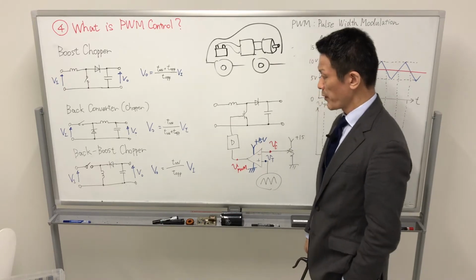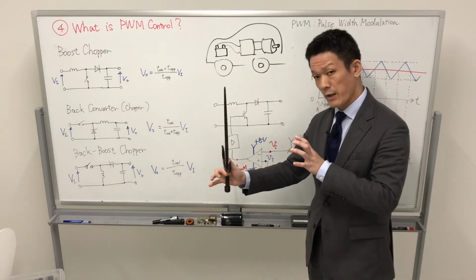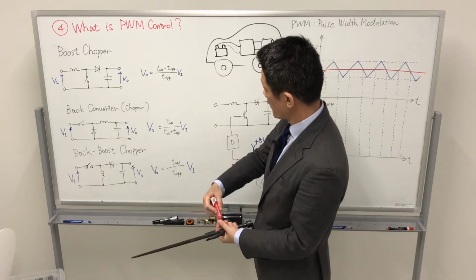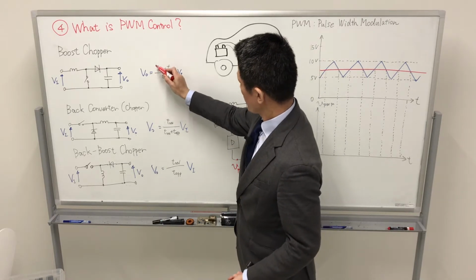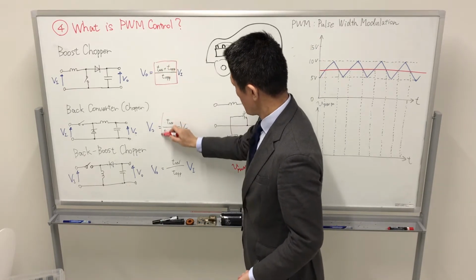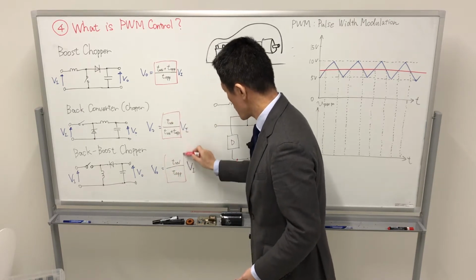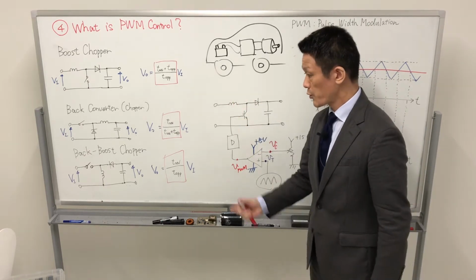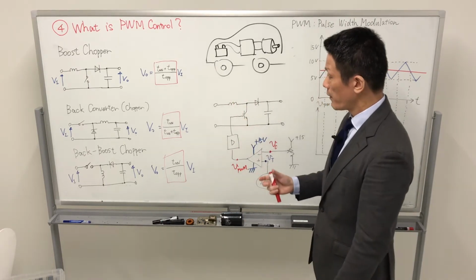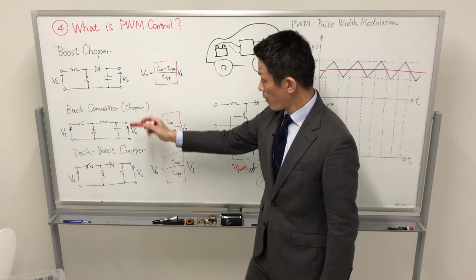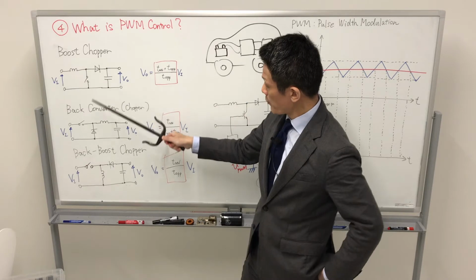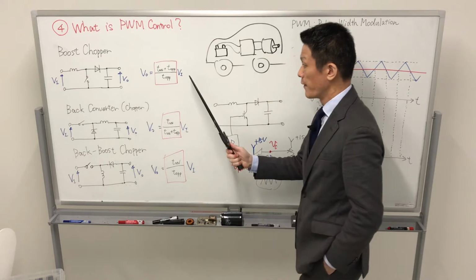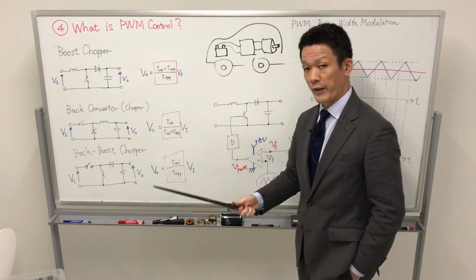The relationship between the input side and output side indicates each other, and the main discussion of these relationships is only the switching timing. Each power semiconductor's turn on and turn off timing influences the output voltage directly.